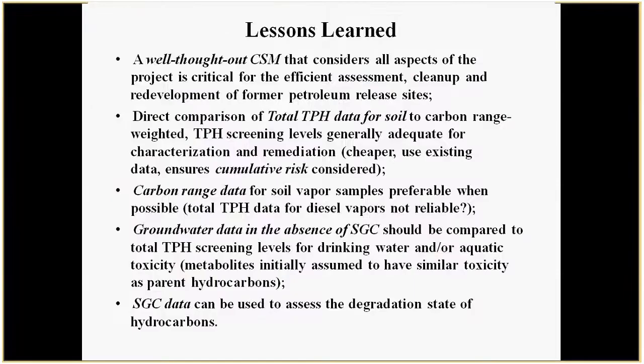Some of the lessons there, lesson one, case study one: you really need a well thought out CSM before you start an investigation. Get your risk assessors involved, get your remediation people involved. A direct comparison of total TPH data in soil, in our experience, is fine to do the job to address all concerns associated with contaminated soil and TPH.